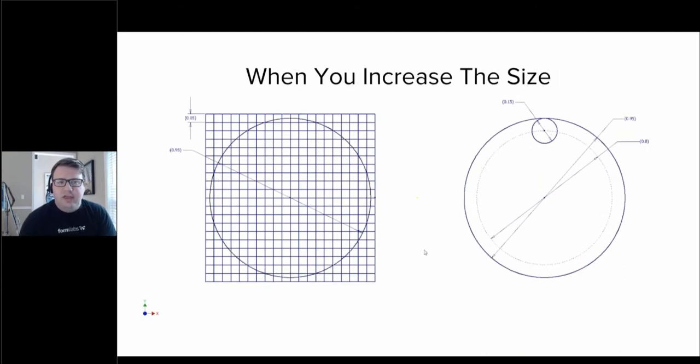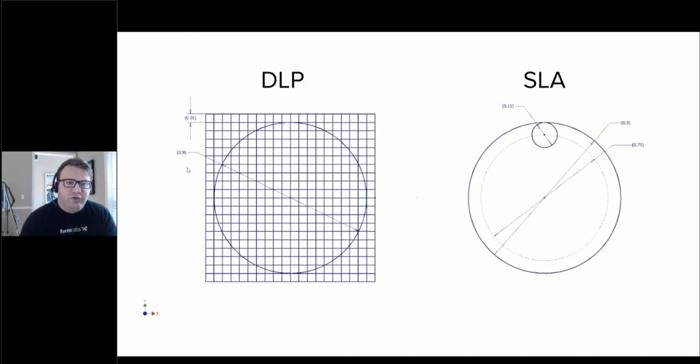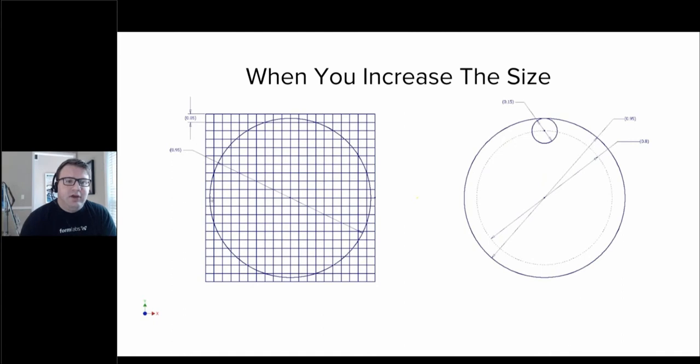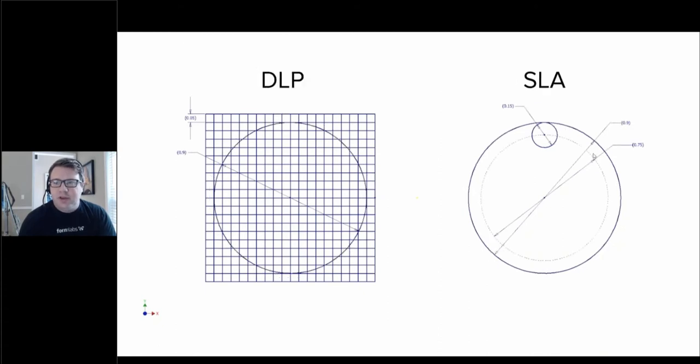And if you were to change the size of the peg to say 0.95 millimeters, you can see where the problem starts to happen. So we'll just skip back to the 0.9 millimeter. You see we're right on the edge of the boundary. You go to 0.95, now you're halfway through the next pixel, and the software is going to have to decide which pixels are turned on or off. And you can see why this starts leading to some challenges for the printer being able to accomplish that difference in fit between an interference and a transition fit, mainly because it can't actually make half a pixel. So in the case of the Form 2, we'll just increase the laser path by 50 microns to produce a slightly larger 0.95 millimeter peg versus a 0.9 millimeter peg.